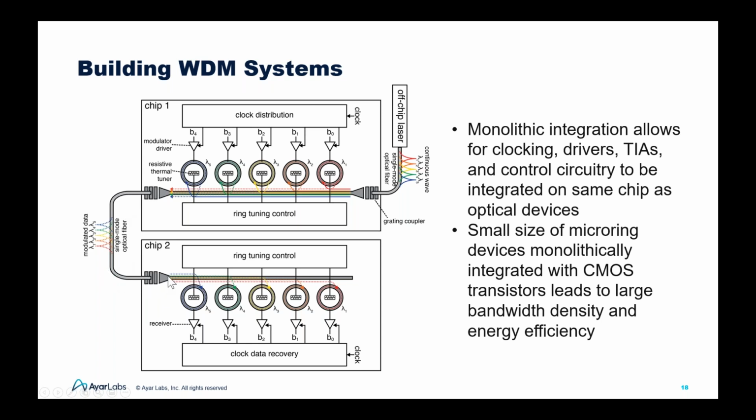And the single fiber is coming here, and the receiver, because it acts like a filter for us too, is going to only pick lambda 5 all the way to lambda 1, and then we pass it to the CDR for electrical communication.